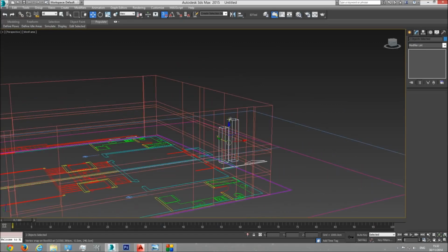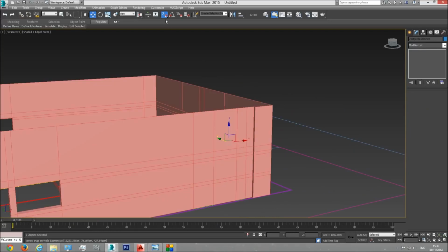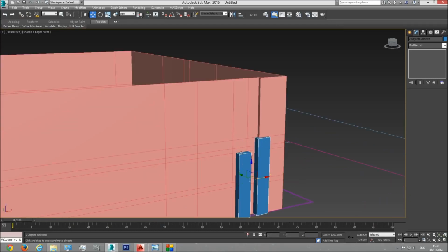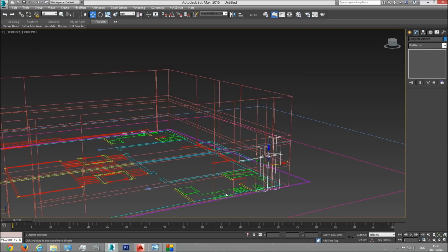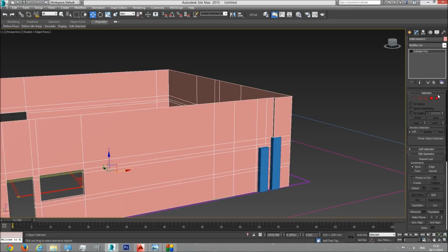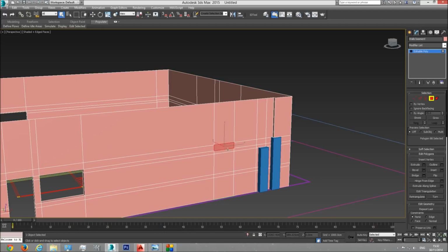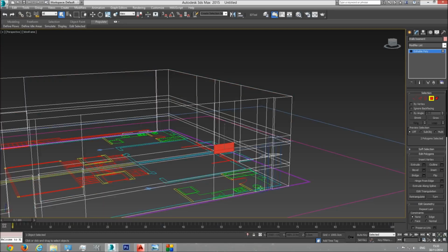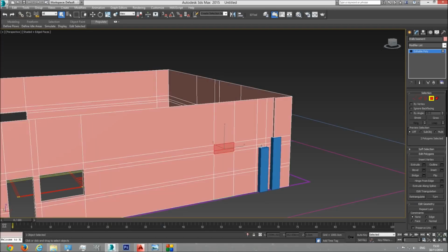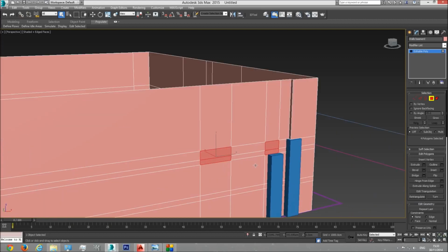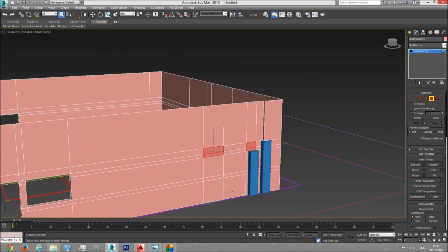Let's move them forward for a second for reference purposes. I'm going to unsnap this, move them here, and you can see in the walls where the lines are crossing. So we have two windows here. The first one in this line, I'm going to select it, 1, 2, because it starts at 206 and finishes at 246. And the other one is here, the bathroom. Again, control, click here and here. So now we have both of these windows selected.